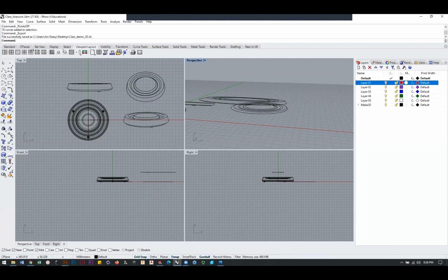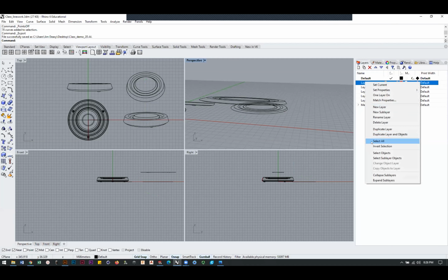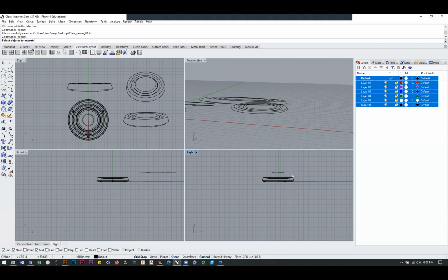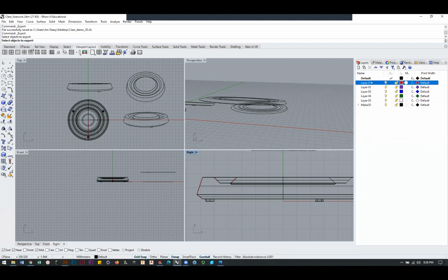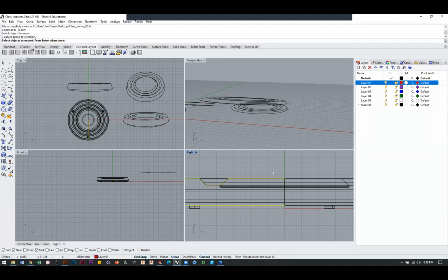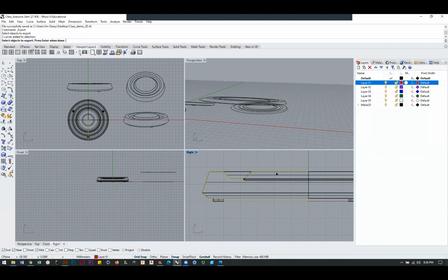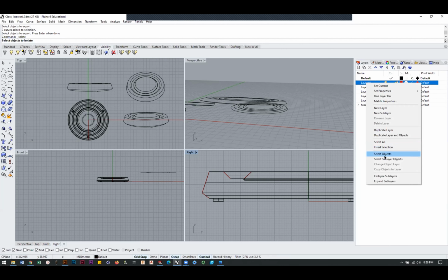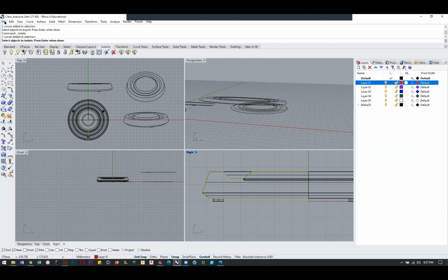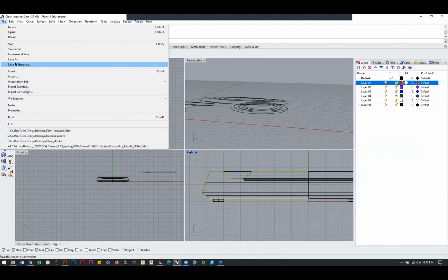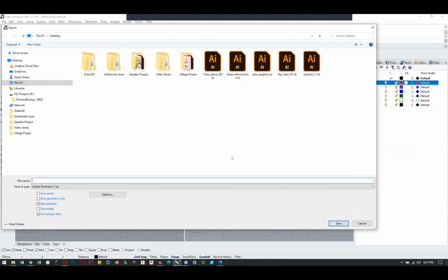So if we take a look at the line work that I used to draw this, let me just zoom in here real quick. Perfect. So here's this bit of line work right here. Okay, that's the curve that we started with. Select objects. Just by selecting that line work there, you can go File and Export Selected, and you can go for an SW transfer line work.